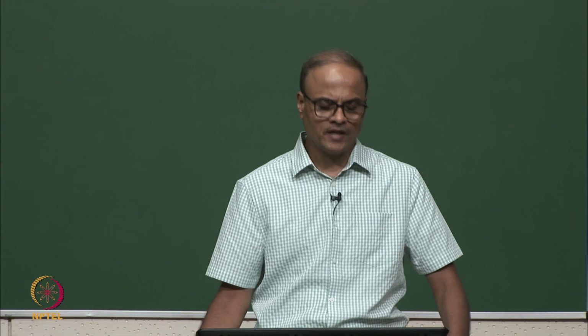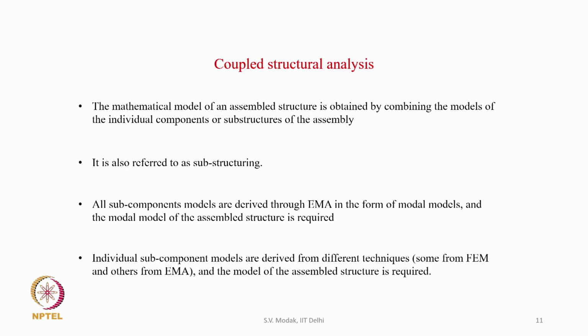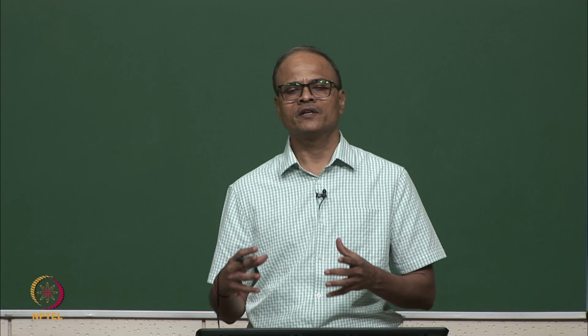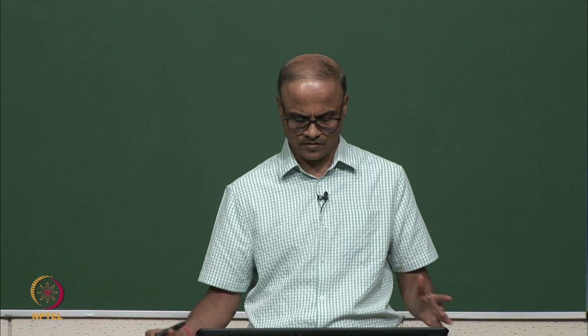One possibility is that all subcomponent models are derived by modal testing, and the models of the individual components are then combined to obtain the model of the complete structure. The second possibility is that the individual subcomponent models come from different techniques. For example, some may be built using the finite element method, and some may be obtained by modal testing, and these models are then combined to obtain the model of the assembled structure. So, this is basically a hybrid approach for coupled structure analysis.